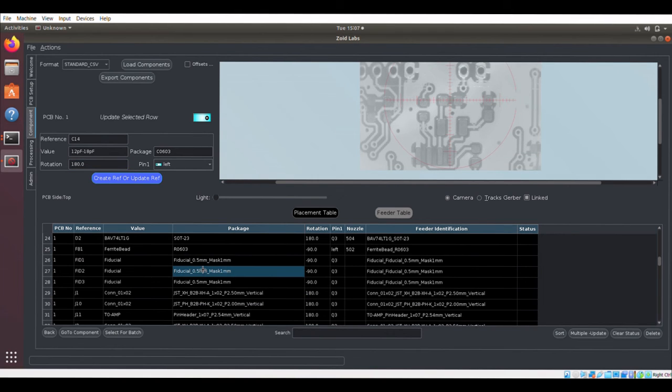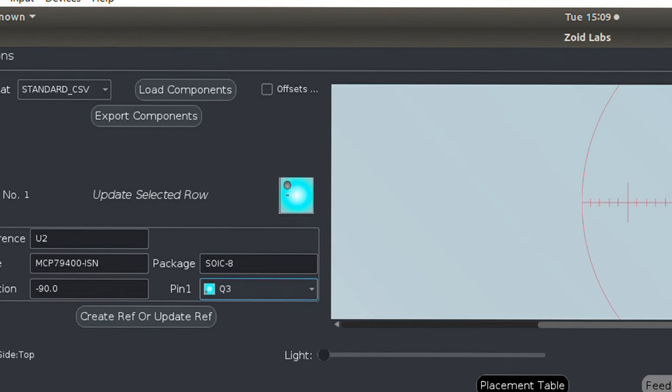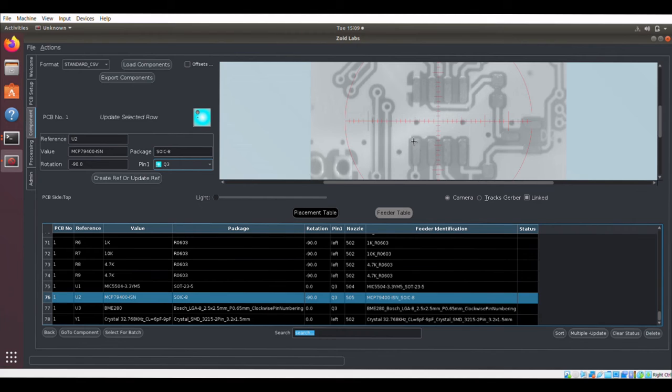Check the same for ICs and update if there is any change. For ICs, the blue square box represents its orientation. The dot's position represents the reference pin position of the IC. As you can see on actual PCB, the orientation of the reference pin is at the bottom left corner, whereas on the image representation of the IC it is at the top left corner.